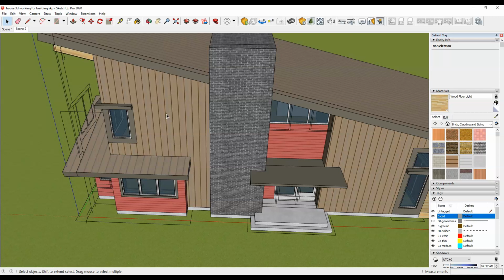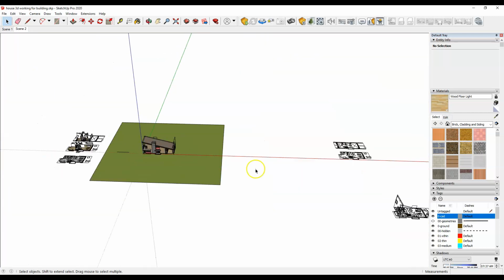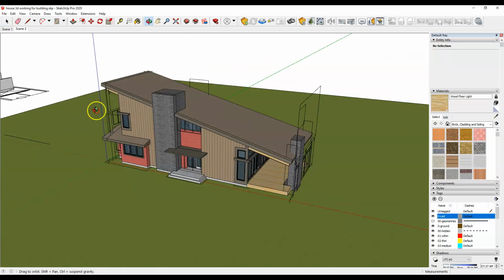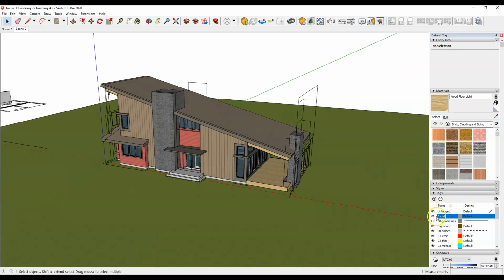And it's all because it has all these different layers or different tags because I used them on different groups. And so generally the best practice in SketchUp is to draw the core object untagged. You can generally keep things untagged unless otherwise they need to be for some reason, right? So that's generally how I work. So in the example of the CAD stuff, because I want to be able to turn on and off the scaffolding after it's modeled, I have that on a layer. So I can simply go on and off just like that, right?